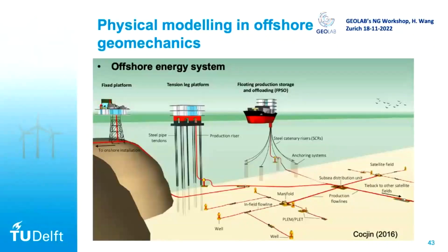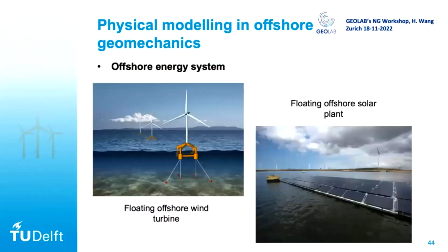Very last, I only showed you some applications of the centrifuge for the monopile, but actually you can do much more using the centrifuge. This is a very nice figure. Using the centrifuge, you can study the foundation of the platform, the pipeline system, the anchor, everything. More importantly, I showed you the bottom-fixed offshore wind, but we believe the future will be more floating offshore wind turbines. Then you have the anchor system, and we also have floating offshore solar plants. So there is a lot you can do in the centrifuge.